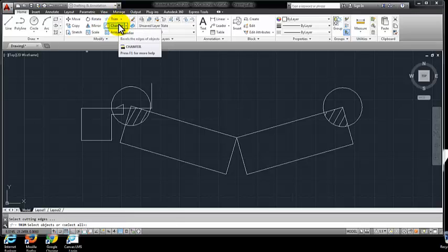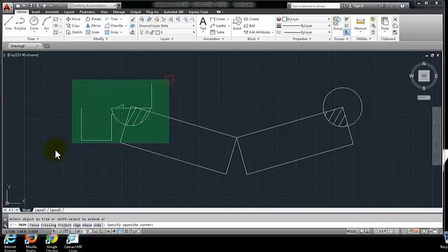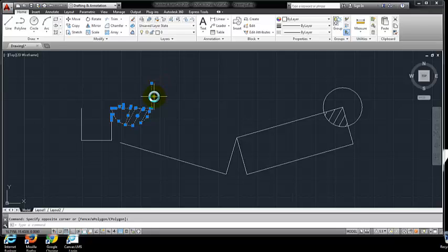Trim's a fun one. Click trim, I click enter, and then anything, you see it's going to come to this line, it's going to come to this line. Before it passes through a crossing line, it'll delete everything there. Bam. Now sometimes it won't, and you'll have to go through and do it individually. But a lot of the times it will. Like if you bring it like this, bring it like this. If you escape out of there, click those, delete them, no big deal.